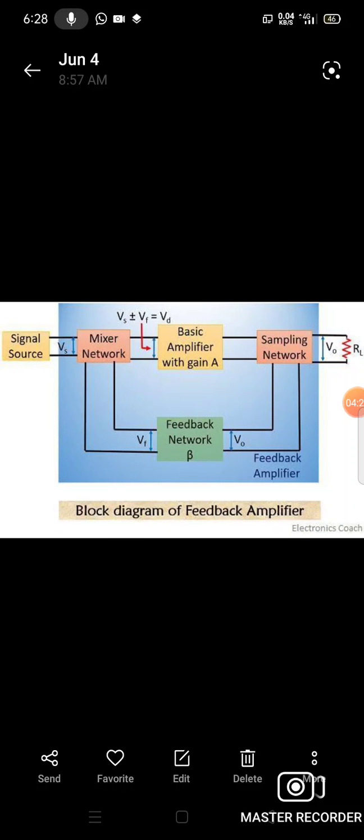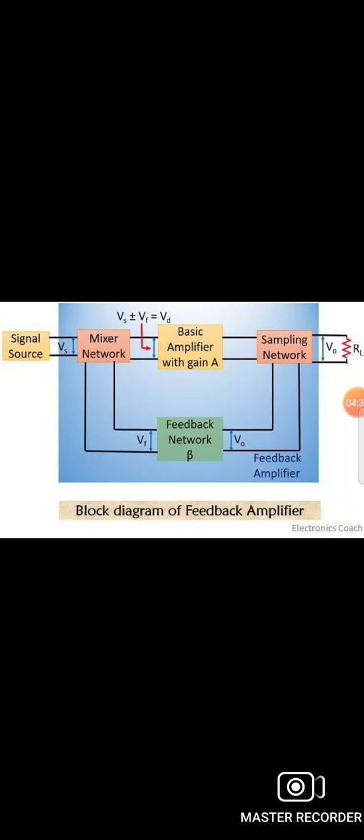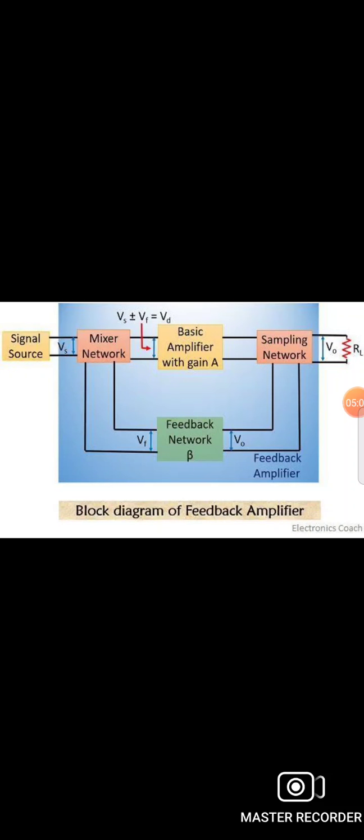With negative feedback in the amplifier circuit, the gain is decreased or reduced, the bandwidth is increased, noise and distortion decrease, and stable operation is maintained between input and output. So these are some important points about the characteristics of the feedback types, right? So negative feedback is better for the amplification operation in the amplifier circuit compared with positive feedback, right?